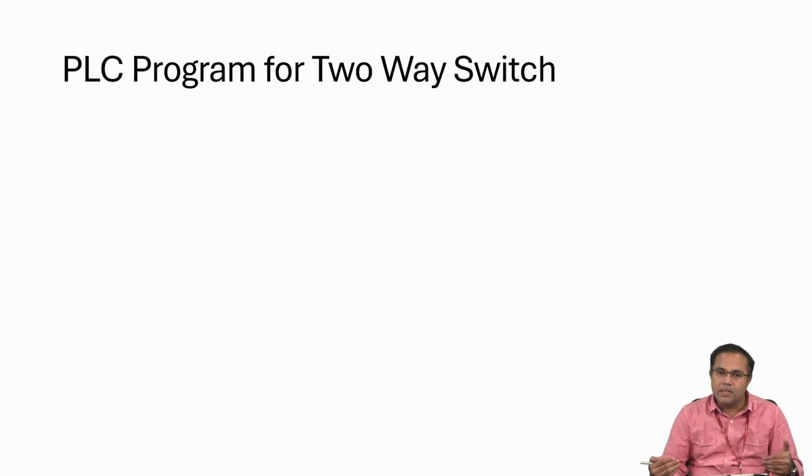Similarly, in PLC, we have a sequential application as well. What happens in a sequential application? There will be some timing. You can schedule, you can delay the output, you can bring some time parameter into the logic. But in the switching application there is no time parameter. Whenever the input changes, instantly the output will change. Understood?